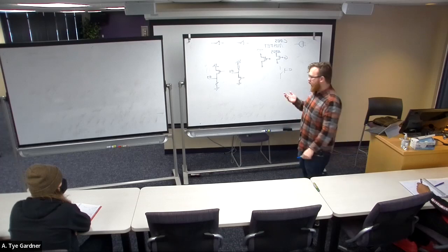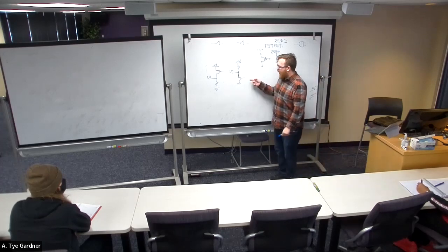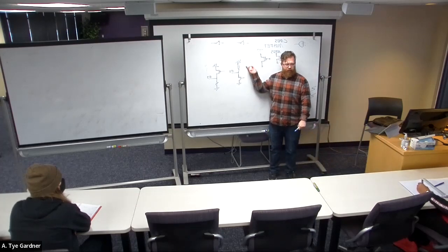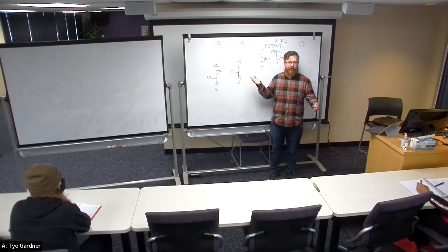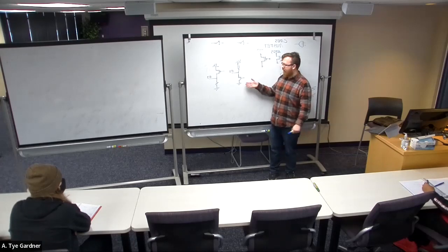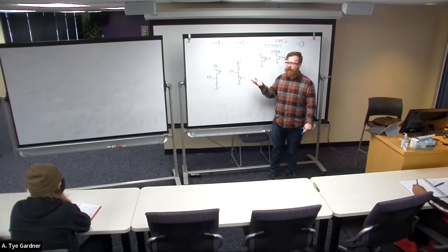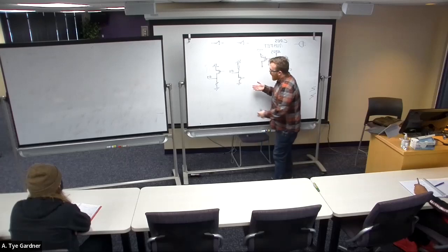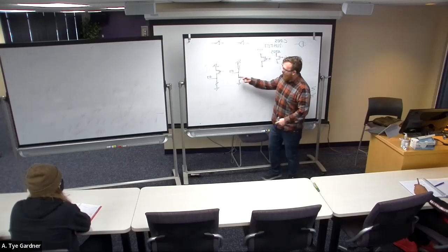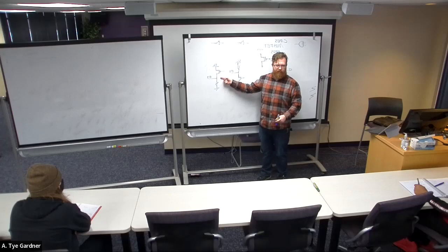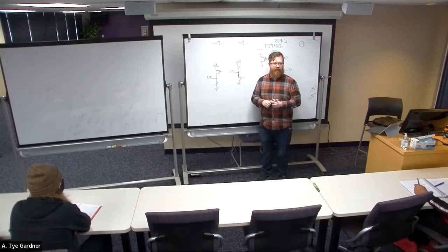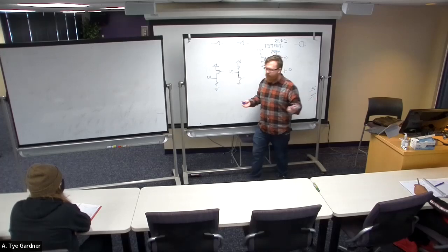So we could write really sophisticated logic that always puts a 0 here to prevent any current from flowing. But that's not really a good solution because then it can't necessarily remember that there was a 0, right? You're basically resetting its knowledge every time. Well, it turns out if this is an inverter and that is an inverter, let's just smash the two together and get rid of our resistors.